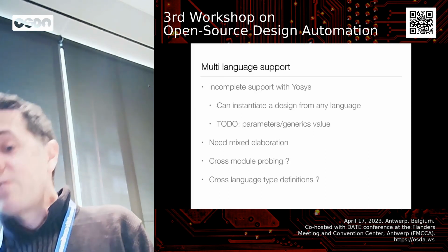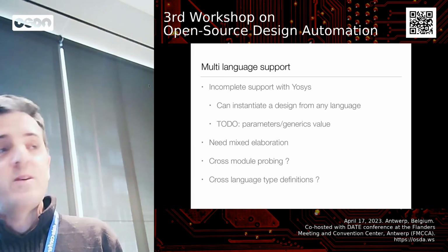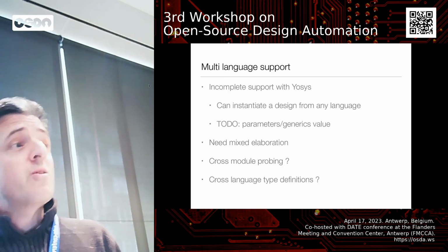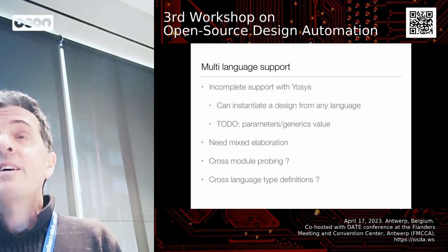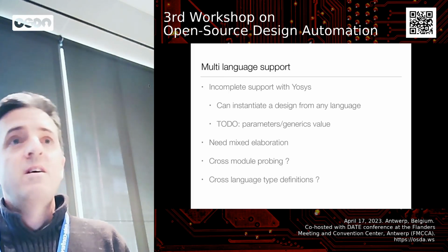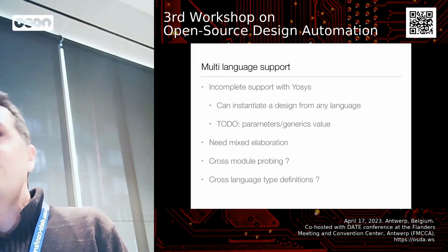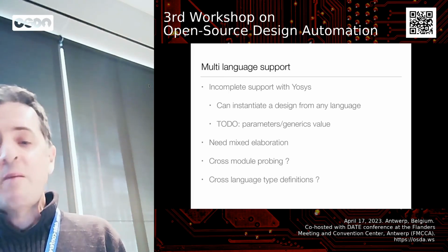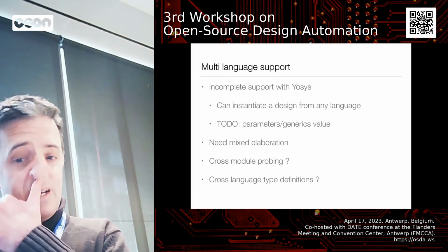Again, we'd like to also support multi-language for synthesis. There is currently incomplete support with Yosys because you can instantiate in VHDL a Verilog design, but there is limited support for parameters or generics.